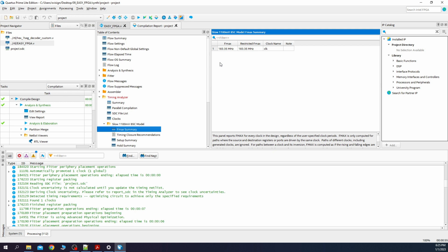Remember, if your design is not a safety critical app that requires an asynchronous reset N, for FPGAs you should always use synchronous reset. This gives you better synthesis results. Also, this should help your logic to meet better timing when the combinational circuit has a very large propagation delay. Let's program the FPGA now.